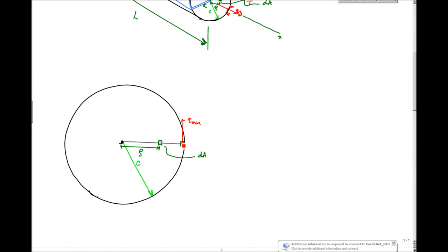And then here, if I take an arbitrary radial distance from the center, I know that I'm going to have some sort of linear relationship, because my deformation is also linear. I know my stress is also linear because Hooke's law is linear. And so here I have some shear stress on this incremental area at some arbitrary radial distance rho away. Here I'll call that tau. And I know that I can relate the two by similar triangles.